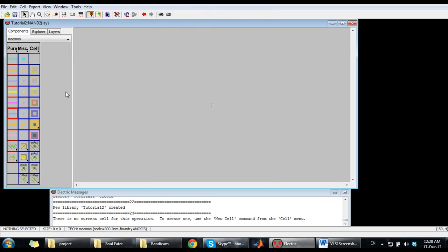So to start with, our basic components are an NMOS, a PMOS, a P-well, an N-well, a P-active, and an N-active. Moreover, you can have different polysilicons. You can have up to 2 polysilicon layers and 6 metal layers. Of course, you can have other things like metal contacts, so that you can go from one metal layer to another.